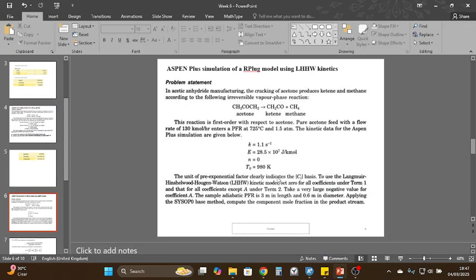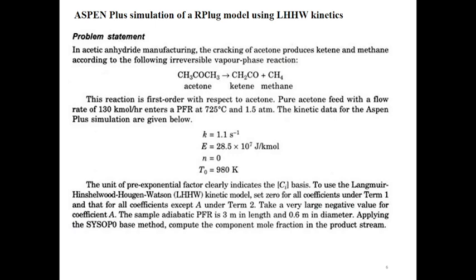So this is also an RPlug model. Over here, we are going to use a different kinetics. Up till now, we were using the power law. Now we are going to use LHHW kinetics. LHHW kinetics is usually used for adsorption problems.